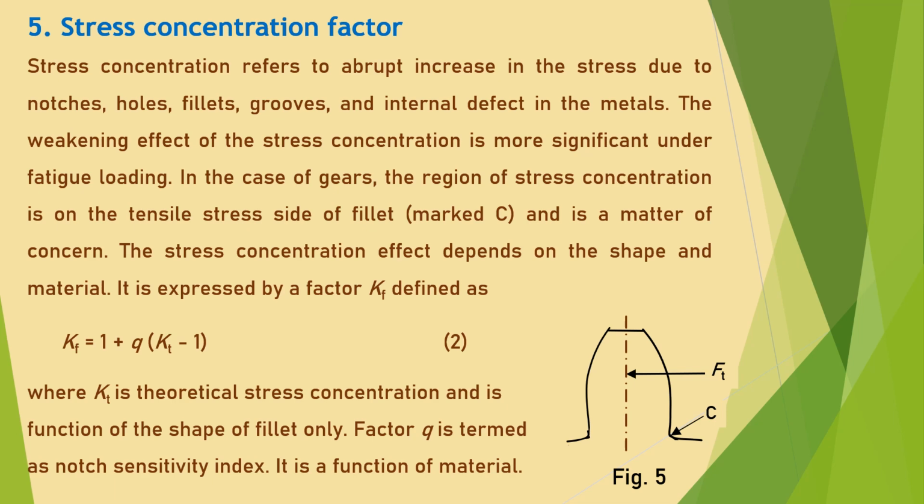The stress concentration effect depends on the shape of the fillet and the material of the gear. It is expressed by a factor Kf defined as Kf equals 1 plus q times Kt minus 1, where Kt is known as the theoretical stress concentration factor and is a function of the shape of the fillet only. Factor q is termed the notch sensitivity index and it is a function of the material.